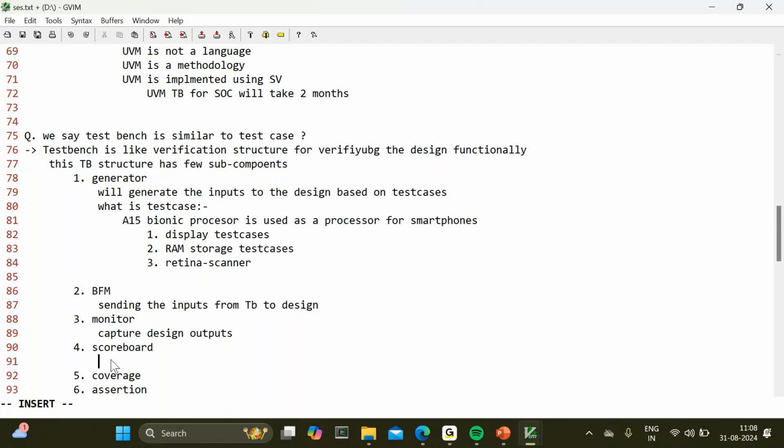Whatever the test bench is doing, the memory write, when memory is being read, see, you are writing something to the design memory. That's the write operation. During the read back, the design output is where we'll be reading the data from the memory. Now I have to compare this memory data output and the memory data input. That comparison is what we do in terms of scoreboard. That is what we call data integrity checks.